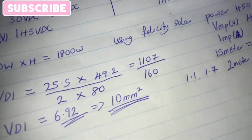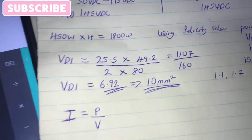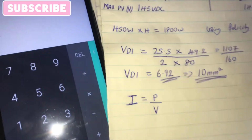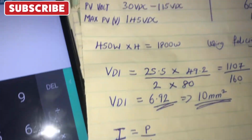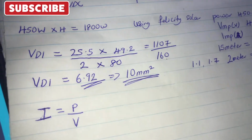Yeah, so this is basically how you calculate the one that's from panel to your charge controller. You will use 10 mm. So let's now calculate from charge controller to battery. You have to bear this in mind. Here we just used the amperage direct, the current direct.